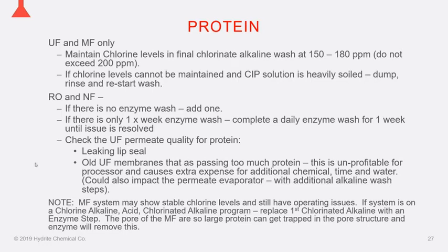to be important. And if you can't maintain them and you've increased the amount of chlorine in the system by boosting it to an amount that totals twice the amount of the original dose, go ahead and dump that solution to the floor and start over, because what you're probably dealing with is protein that's been removed from the membrane surface, but is still circulating in solution and eating up that chlorine. And that's not the target we want to go after. And so, the only way to get after the foulant that's actually on the membrane is to dump the dirty solution so we can get something in there that's actually attacking the problem.